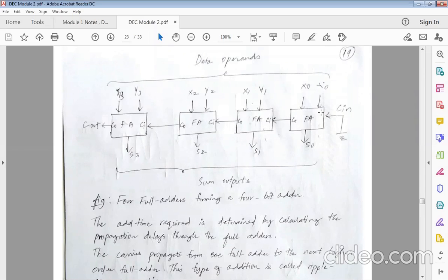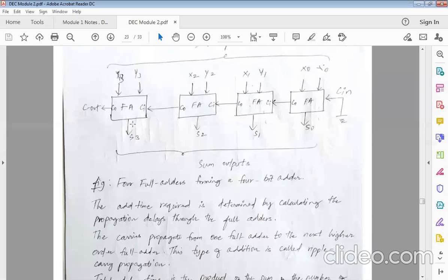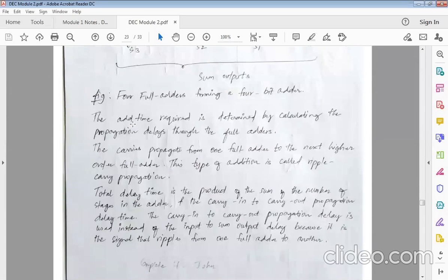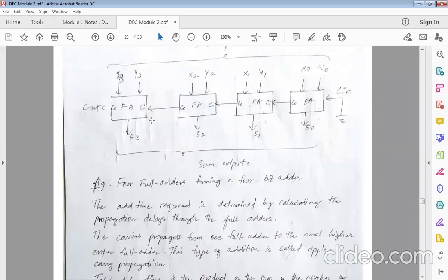In the first stage we do not have any carry in, and when we get 1, 1, that is when a carry gets generated. Then it needs to go to the next stage, and then the next stage. Due to this, there is going to be a lot of delay for the propagation of carry. So we will see what can be done in order to get this rectified.